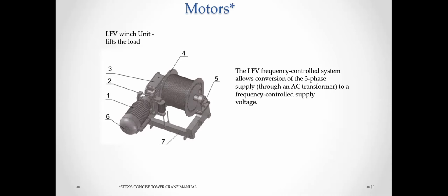And how much they can lift depends on the model, but the typical tower crane can have a maximum unsupported height of 80 meters, and then the maximum reach will go to 70 meters. And if you want to lift, the capacity is at least 19.8 tons. And the counterweight depends on the design also, but in the typical tower crane being used in New York, it will be about 20 tons.